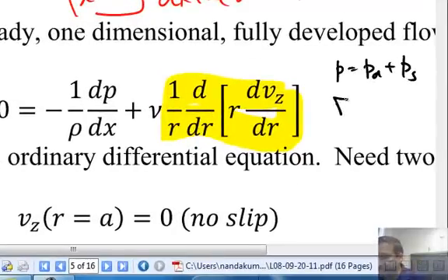And when you have the gradient of P, you can write this as gradient of PD plus gradient of PS, and gradient of PS plus rho G is equal to 0. This sloppy use of terminology you will find in all the fluid mechanics books. You don't write PD, but when you don't see a G in it, you interpret P as dynamic pressure.